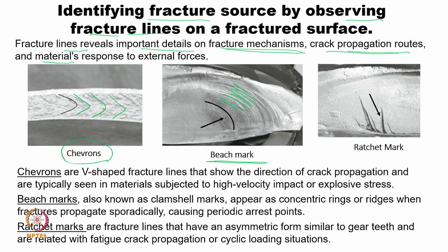When I was presenting this slide, and in one of the earlier lectures also, I mentioned that if the plastic limit goes beyond a certain limit, the load is continuously increasing, and the stresses are going along the plastic limits, then there is a possibility of rupture marks. These rupture marks are very sharp depressions, and you can look at this like the gear teeth on a surface. So, this indicates very clearly that the load is substantially high.